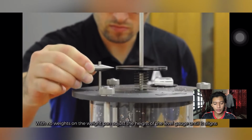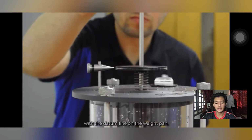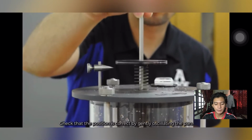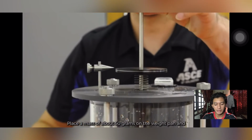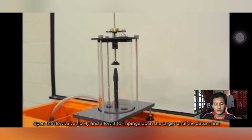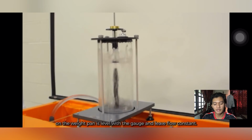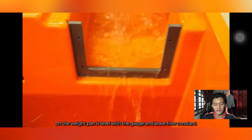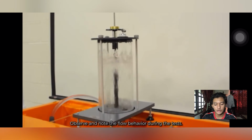With no weight on the weight pan, adjust the height of the level gauge until it is aligned with the datum line on the weight pan. Check the position is correct by gently oscillating the pan. Place a mass of about 50 grams on the weight pan and open the bench valve to produce the flow. Open the flow valve slowly and allow it to impinge upon the target until the datum line on the weight pan is level with the gauge, and leave the flow constant. Observe and note the flow behavior during the test.